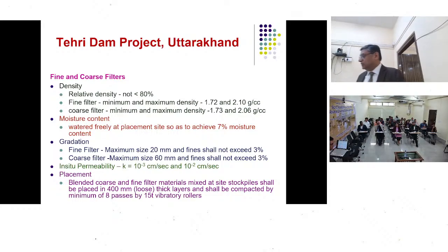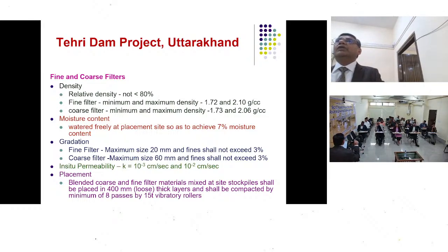And suppose this is my placement site. Far off from that place, we had pumping sets wherein maybe some 200 liter or 300 liter of water is poured into the truck, well sprinkled over the whole area of the truck. And then this truck used to go into the placement site. So when we come to the placement site, your moisture content error is maybe up to a level of 1 or 2% only. So 1 or 2% of moisture content error can be taken care of at the site itself.